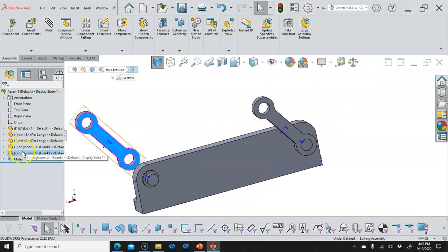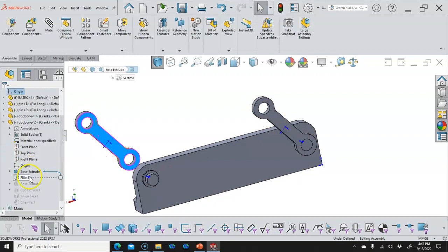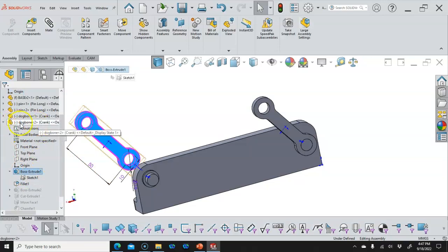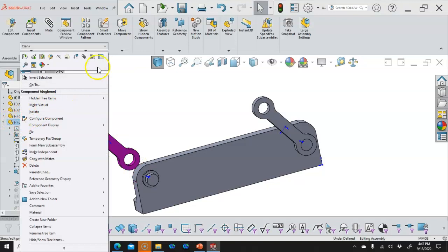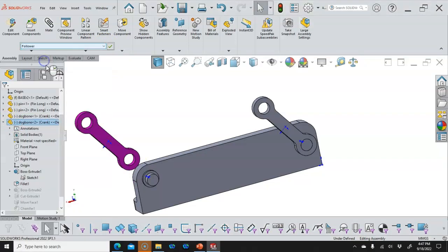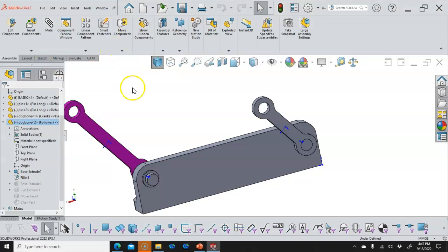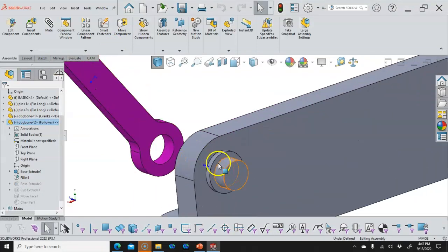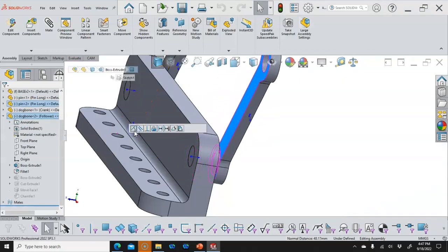And hopefully that length works. We should be able to double click on it and get the 80. So no, it didn't. Oh, I didn't hit the check mark. So we'll go to follower, check mark, and it adjusts in size. So the face, can rotate around, control select the face, go coincident. Pretty close together is going to make it hard to select, so select, we'll move it, and then select, control select concentric, and once you get into the rhythm, this will go pretty quick.